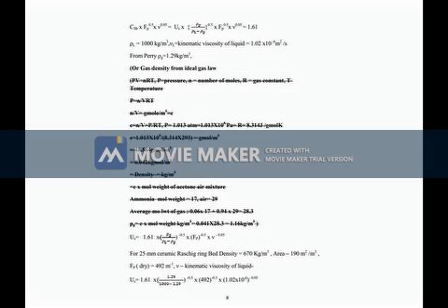So what will be left? 5% only will be left in the air. So 0.05 into Y1, that is capital Y1, 0.064, you will get 0.0032. Then you find out the mole fraction, small y2 is equal to Y2 by 1 plus Y2. That's again also 0.0032 only, being a very small quantity. Then solvent is pure water, and x2 is equal to 0.